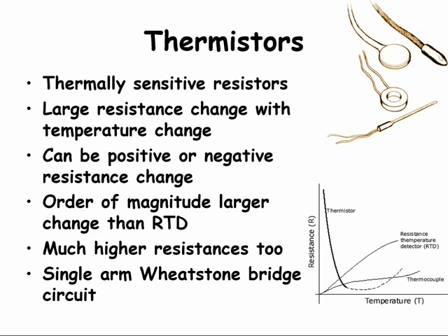The next type of thermal temperature measuring sensor that I want to discuss is thermistors. They are like RTDs in that the resistance changes as a function of temperature. However, thermistors have large resistance changes compared to the small resistance changes that RTDs have. Thermistor temperature coefficients are commonly an order of magnitude, 10 times, more than the RTD coefficient. Thermistors are made of silver sulfide or metallic oxides.